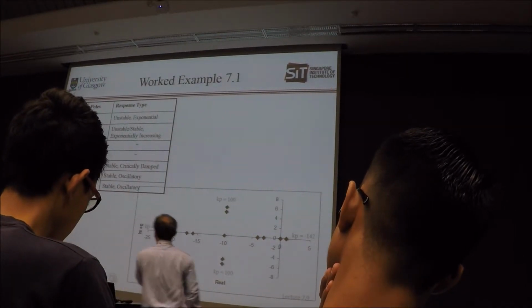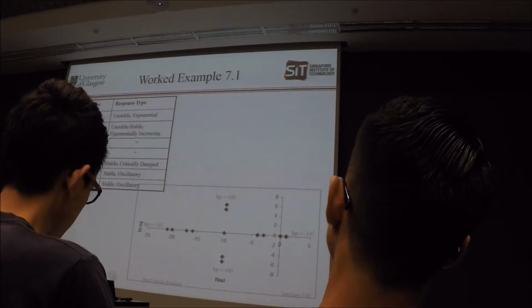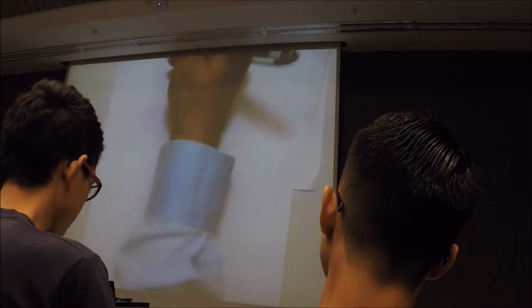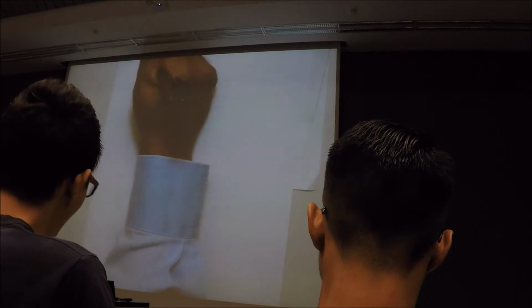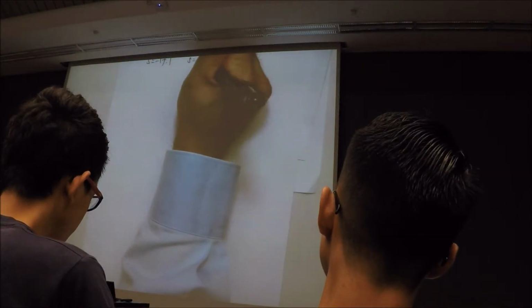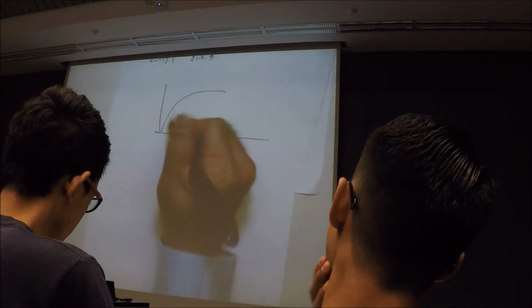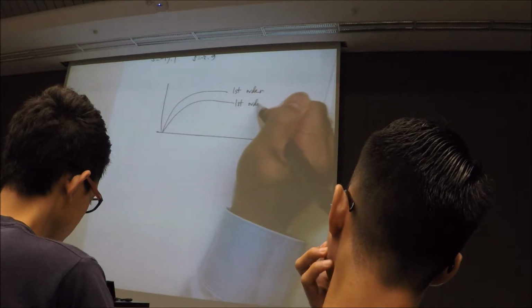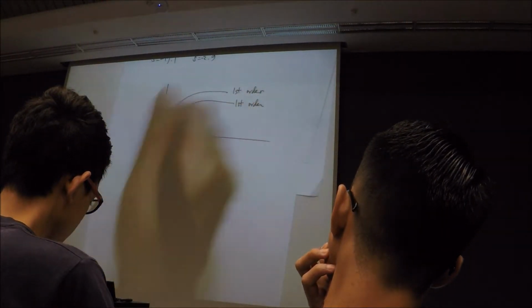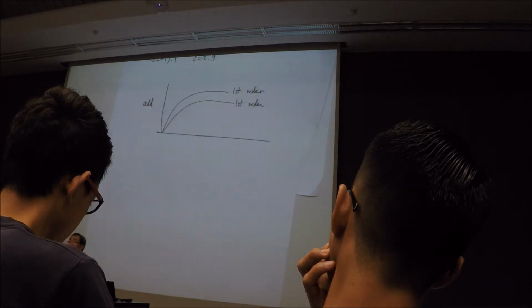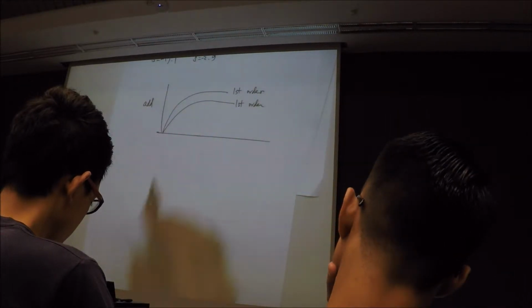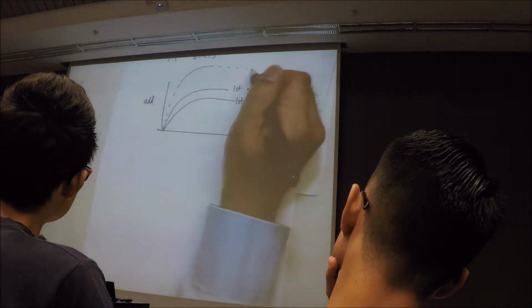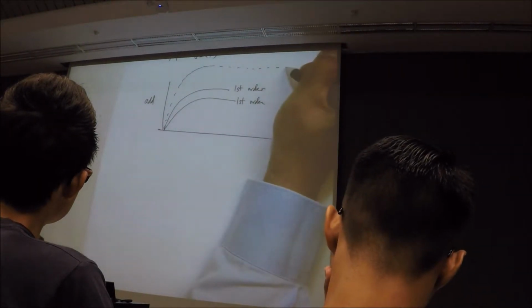So if you have poles at minus 17.1 and minus 2.9, how would the response look? It all depends on the transfer function that you have, but typically you can think of the step response as two first order responses. This one is first order, and this is also first order. For a second order system, you just add them, that means you superimpose them onto each other, and that will be the end result. So if that is the case, then you actually get something like this.